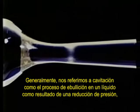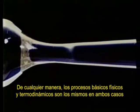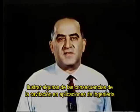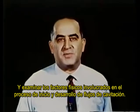Generally, we refer to cavitation as the process of boiling in a liquid as a result of pressure reduction, rather than by external heat addition. However, the basic physical and thermodynamic processes are the same in both cases. In this film, we will see the various forms of cavitation, illustrate some of the consequences of cavitation in engineering applications, and examine the physical factors involved in the process of inception and development of cavitating flows.